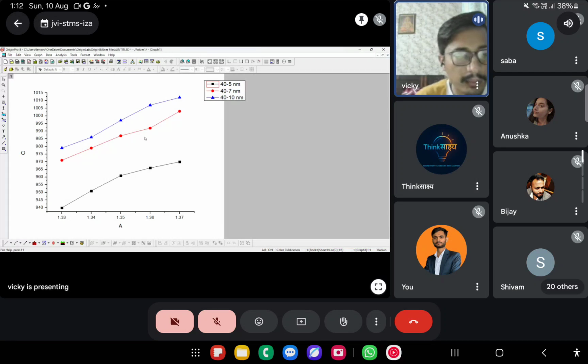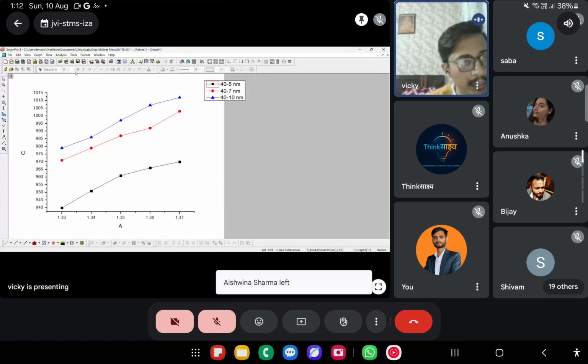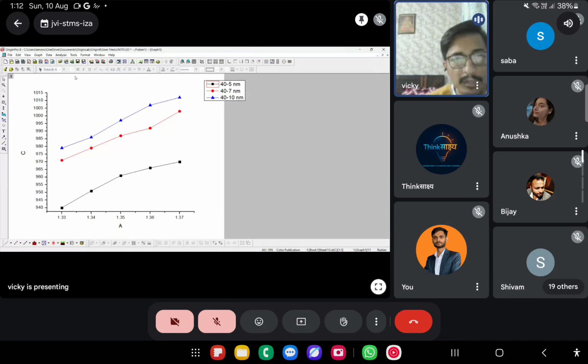Now suppose I want to do the linear fitting. I can directly go to the Analysis menu, right? We have different options there. You can see we have mathematics, like trace interpolation, simple math, normalize, differentiate, integrate. You can do much more things. Exploration is also there, data manipulation is there, and the fitting part is also there. The fitting part is basically fit linear, because I want to do a linear fitting. I can select this, but I will show you what the various options are.